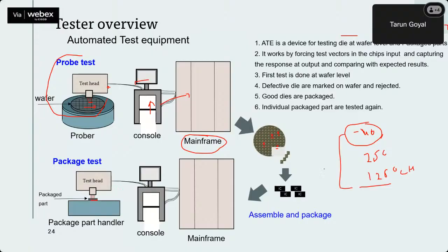We call it 3T, tri-temp testing. We also do matrix testing, because during wafer manufacturing there can be multiple process corners like slow wafers, fast wafers, FS, and so on. We call these matrix units and tri-temp. We do all these tests at cold, hot, and room temperature to ensure that we are detecting all manufacturing defects.